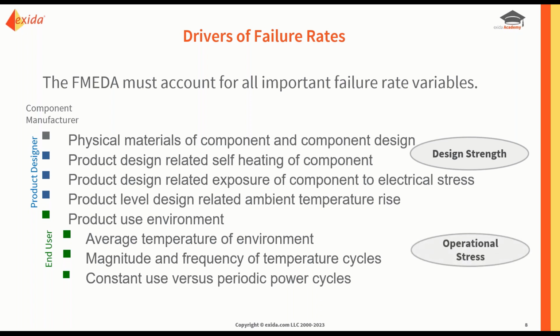And the second one is the operational stress, and this is comprised of the average temperature of the environment, the magnitude and frequency of the temperature cycles, and constant use versus periodic power cycles. So it's these 2 stressors that are the main drivers for our failure rates.